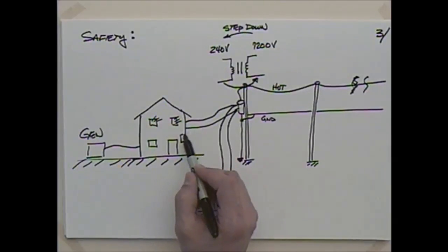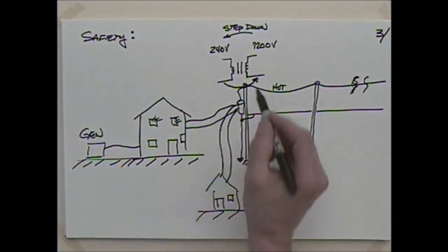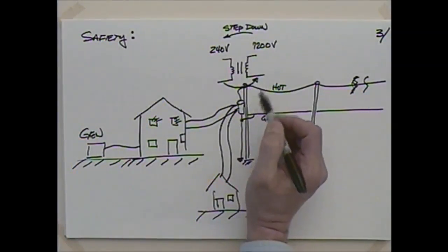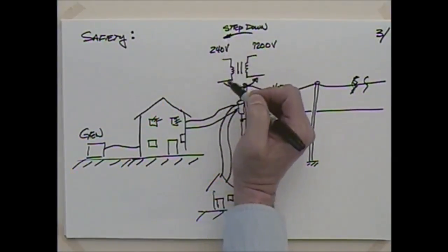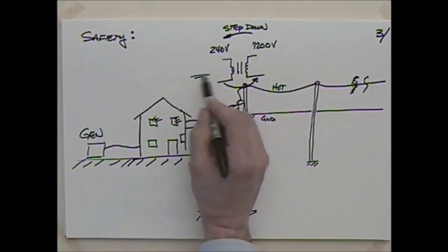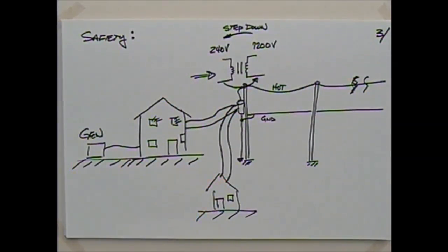But if you turn off the main breaker, it won't backfeed back out of the house. So you have to be really careful of this. Transformers will step up and step down. And when we think of a transformer out there at the street normally stepping down, if you try and backfeed this with power from the generator, it's going to step it back up and could kill someone when they're trying to fix your lines, which they get pretty upset about for proper reasons.